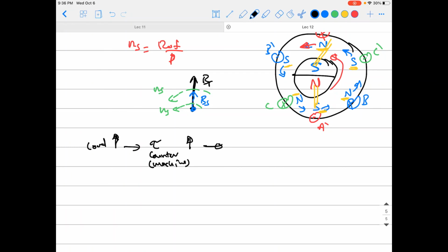And that means the speed of the rotor will go down, but transiently. That means it will go down for a fraction of a second. But our governor, our control system, will restore it back to its value. Like we said before, we cannot let the rotor speed go down. Otherwise, that means the frequency will go down, and we cannot let this happen.